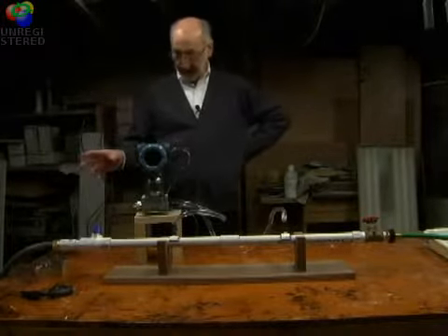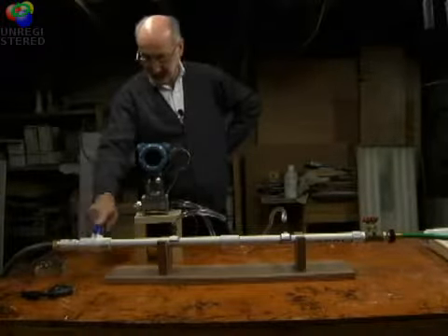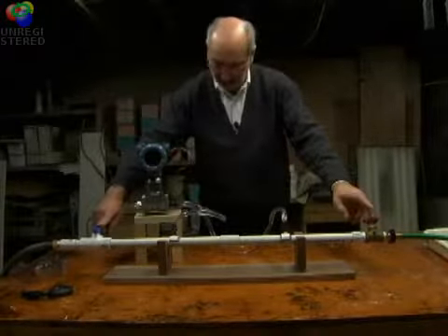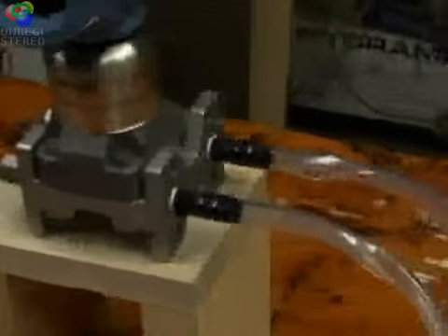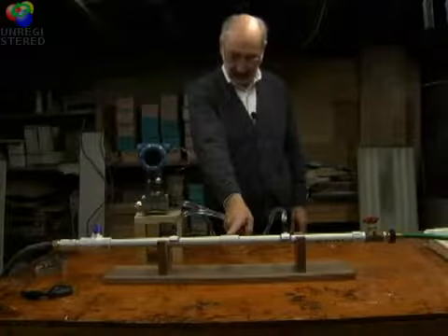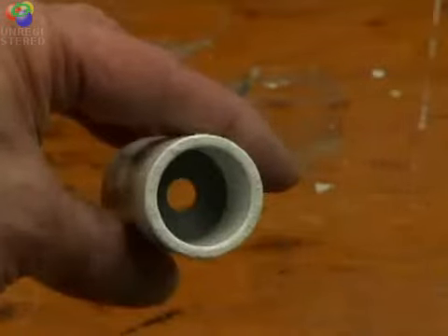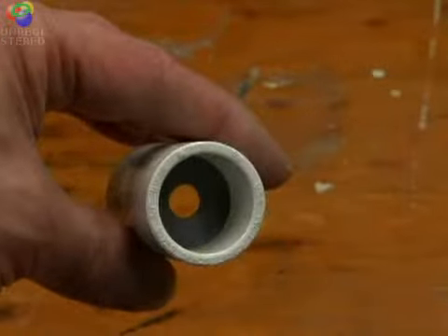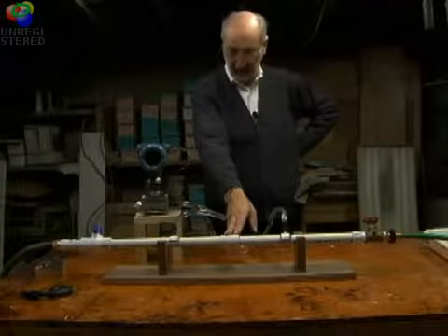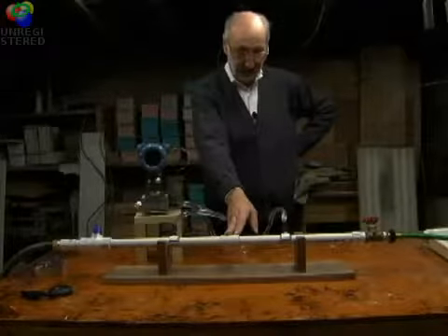What we've got is a water supply, happens to be by garden hose, coming to a shutoff valve and then to this straight section of pipe. What you'll see is we have two impulse lines connected to our 3051 differential pressure meter. Then there's also this union here in the middle of the pipe, this coupling. And inside the coupling is a small disc with a hole in it that's only 3/8 of an inch in diameter, which is considerably smaller than the inside diameter of the pipe. So what we have done in effect is created an obstruction in the pipe which restricts the flow to some extent but does not stop it entirely.